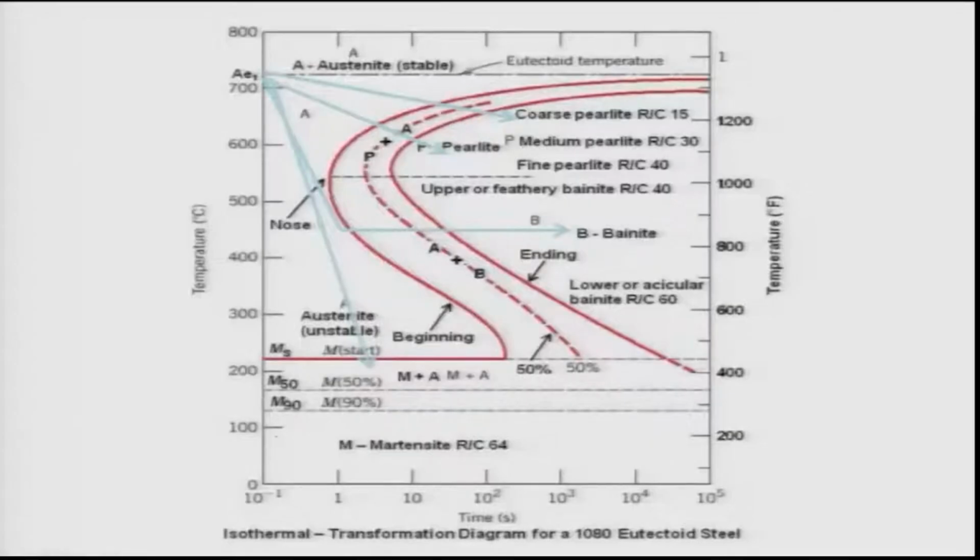If we quench to an oil bath at 150 degrees Celsius, then it will lead to 50% to 60% martensite. And once it is quenched below 100 degrees Celsius, that is, suppose at room temperature 30 degrees Celsius, then almost 97%, 98% martensite will form.